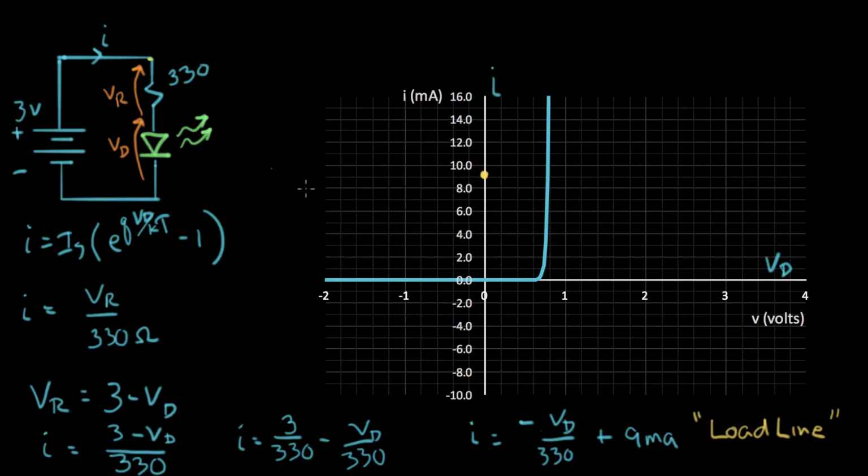And what I'm actually going to do is just look at my circuit and figure this out in my head. I equals 0 means there's no current in this resistor, which means there's no voltage drop across that resistor. And that means that this voltage here is the same as this voltage here. And I know the voltage here is 3 volts, because I know the current is 0.